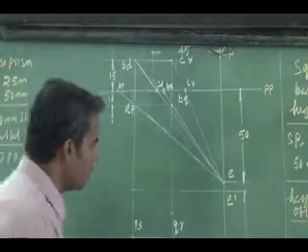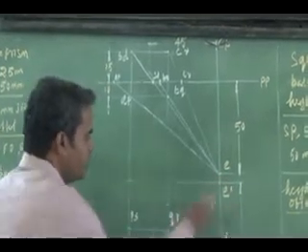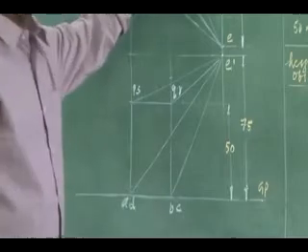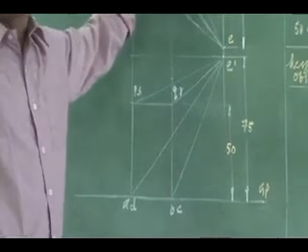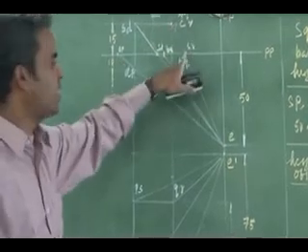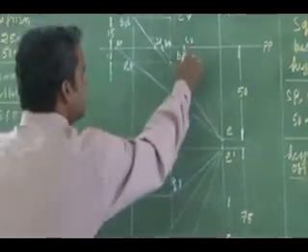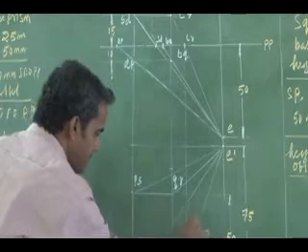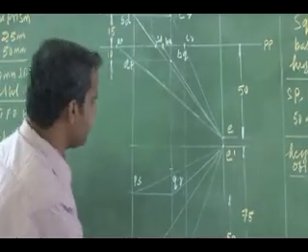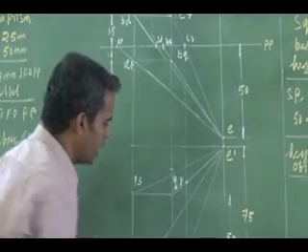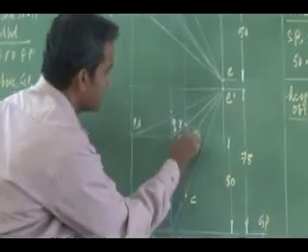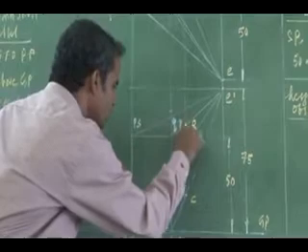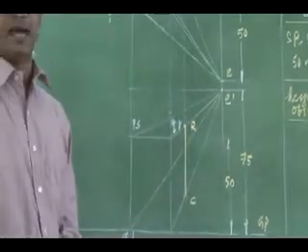Now you draw the visual ray line for your front view. Now, listen carefully. I am going to get the perspective location of CR. HCR, I have the intercept here, CR. So I am just projecting that. Wherever it intersects, C and R, C I have here, R I have here. So that is the perspective location of C and R. So this is my C, this is my R. So I have the perspective view of HCR.